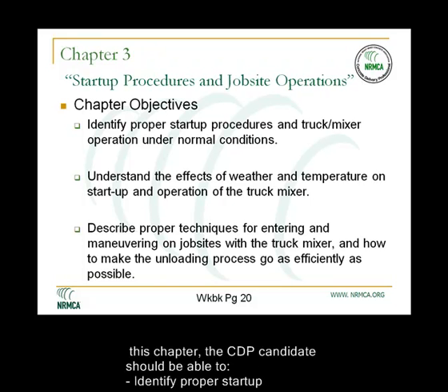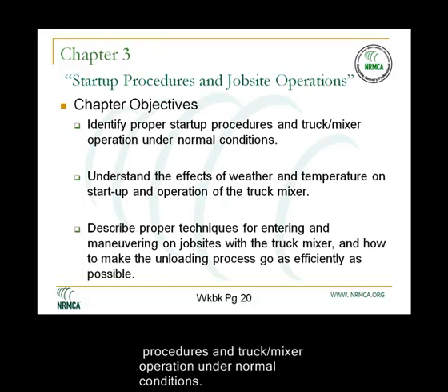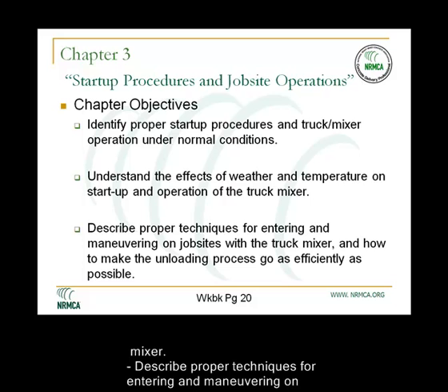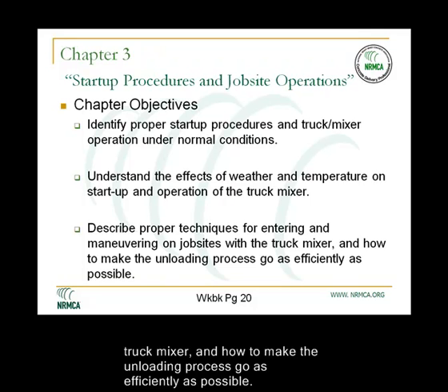Chapter Objectives. After studying this chapter, the CDP candidate should be able to identify proper startup procedures and truck mixer operation under normal conditions, understand the effects of weather and temperature on startup and operation of the truck mixer, describe proper techniques for entering and maneuvering on job sites with the truck mixer, and how to make the unloading process go as efficiently as possible.